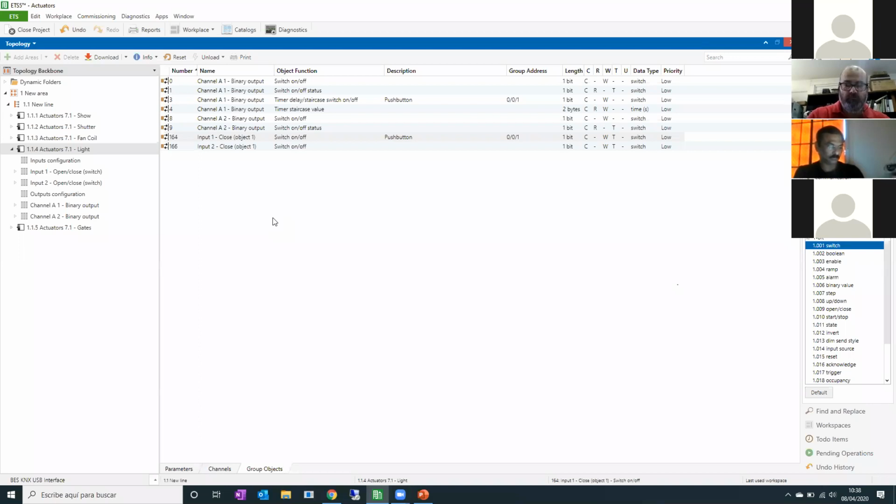As you know, in our catalog, we have the KNX sensors, but we also have conventional sensors. Those conventional sensors you can connect to the digital inputs, and you can use them to detect any technical alarm you consider, and we can convert that detection to a KNX telegram. So it's also important to clarify that digital inputs can be used for push buttons or also for conventional sensors that you can find in our catalog.